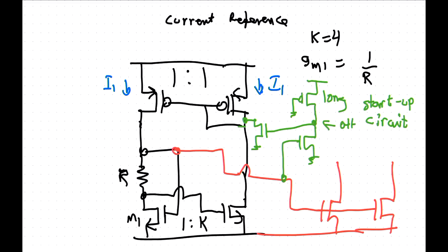Well, that depends on what it is that you're interested in. In most cases, your input comes at the gate, so you should really move that noise onto the gate. So what you can do is make an input noise here, which is now 4kT gamma 1 on gm.